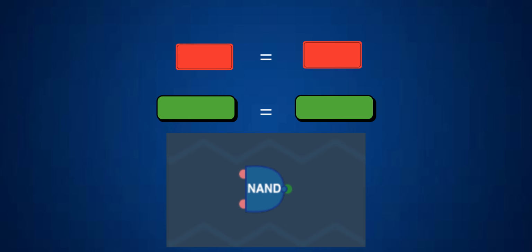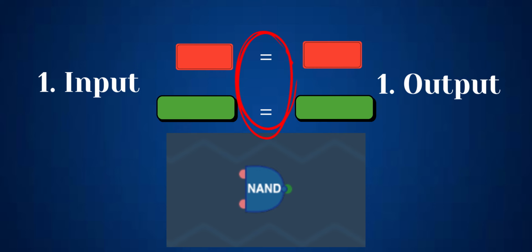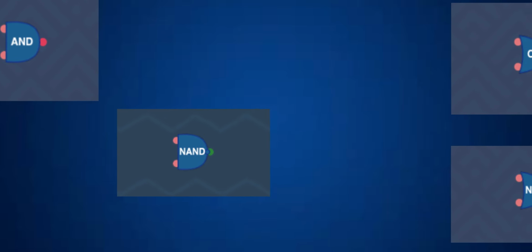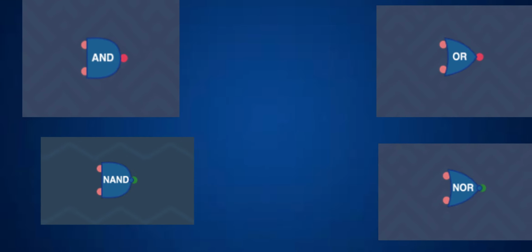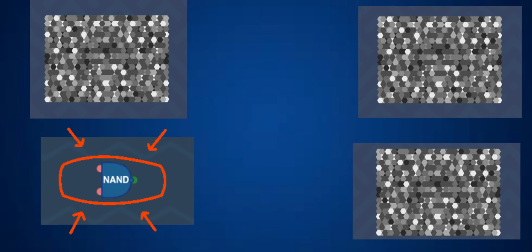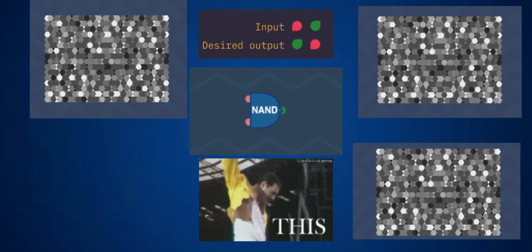Now, an important detail here. A single input only gives us one variable. There's nothing to decide. But with two inputs, we get a combination of states that the circuit can actually react to. That's exactly how the NAND gate is built. Two inputs, one output. Depending on the combination of both inputs, the output changes. Since every component decides its output differently based on its two inputs, firstly, it's important to really internalize the NAND gate and how it behaves. Because our next goal, inverting the input to get the opposite output, requires exactly this component.